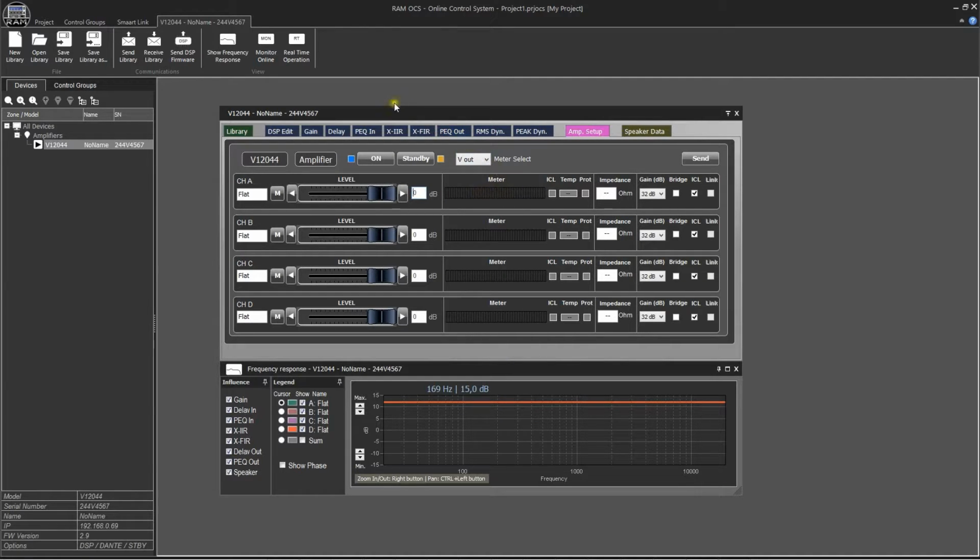To see this VU meter, we should always activate the Monitor Online function from the top amplifier menu. The values we can see on the VU meter are the output voltage value VOUT, the amplifier input signal VIN, output channel temperature temp, or optionally output current IOUT. We also have 3 indicator LEDs for ICL anti-clip system activation, temp heat protection, and PROT system protection activation.